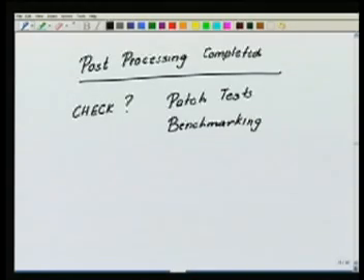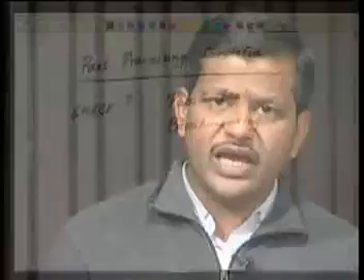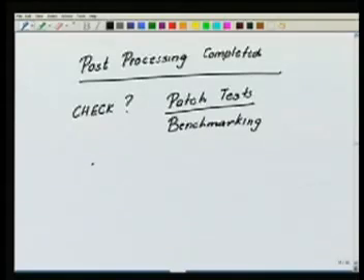What is the basic idea in all these is that we take problems for which we can get the exact solution. And then we go and try to solve these problems and we see whether our finite element solution is close to the exact solution. It should not be too far away. If it is too far away, there is some problem. In fact, in the patch test, we can construct, at least for the case k naught equal to 0, let us say, EA is equal to constant.